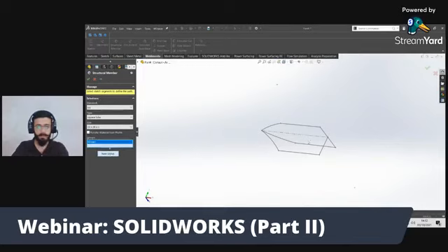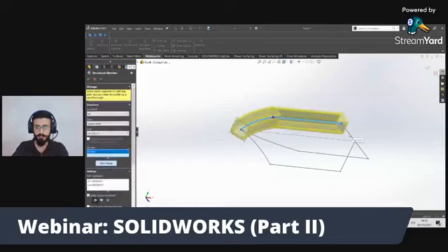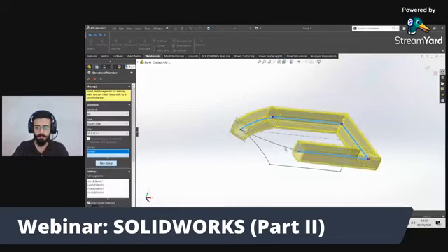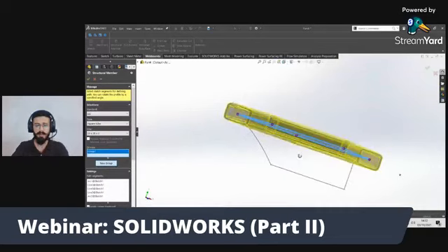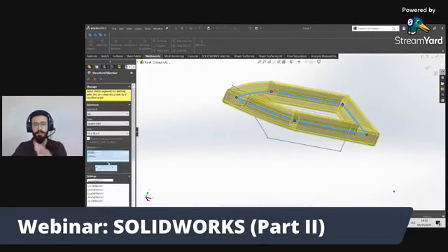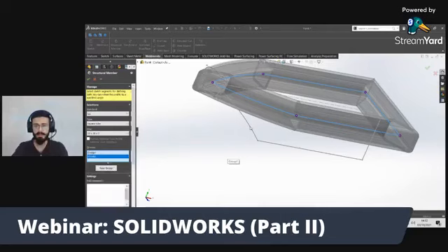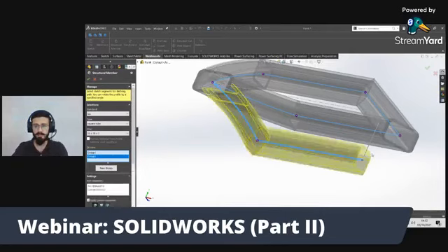And then group one. And see, the first sketch was group one, and now try to select the second. It can't be selected. We can't select the second one. Just create a new group. For the next sketch, create a new group, then select the next sketch.